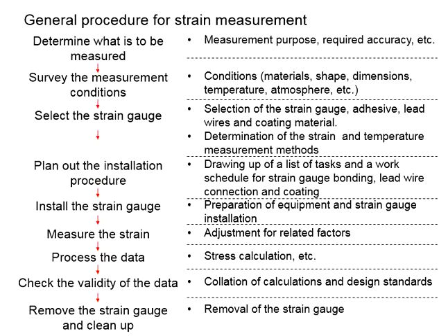Follow the standard procedures of installing the strain gauge. There is a series of strain gauge, another series of adhesive, and also various types of coating materials. Know the proper handling method for the strain gauge. Strictly abide by the installation procedures so that the strain gauge is firmly attached to the test specimen, well protected, and remains in good condition so that you can acquire result from the strain gauge during testing.